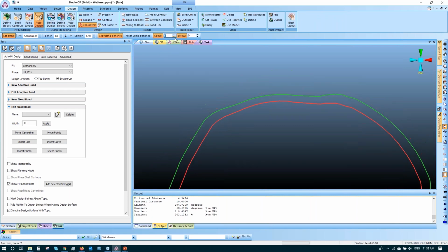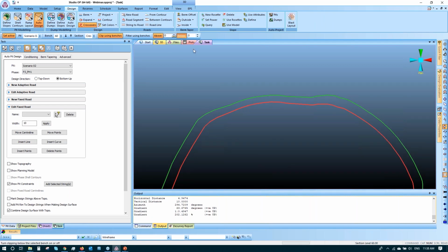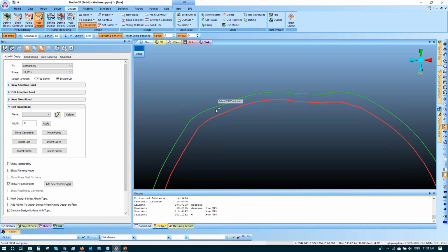Now I will come one below, zero above again, and then I will check this area over here. That is the area where I'm expecting changes. So I will check around here. Here I have an azimuth of 337 and a horizontal distance of 12 meters. So in the range of azimuths from 310 to the azimuth 20, we have a face angle of 60 and a horizontal distance or berm width of 12 meters. So it is as expected.